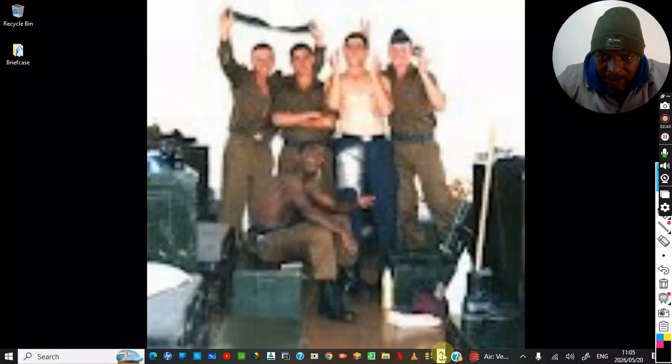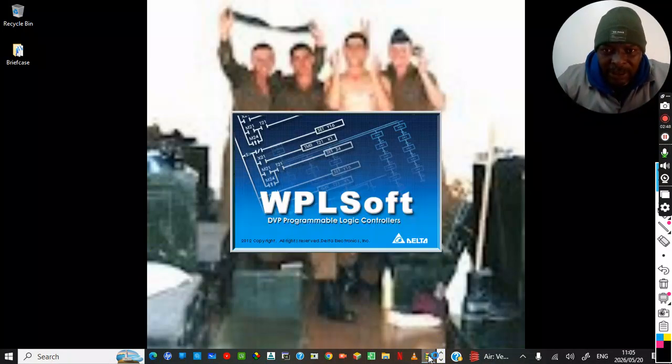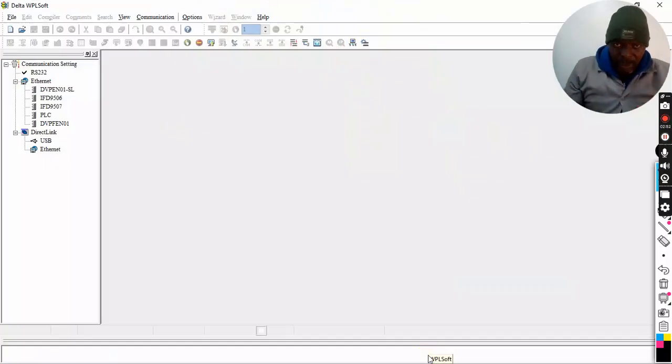Let's bring in our PLC. We'll go down and get our WPLSoft there, and then I want to use this platform, before I open a new page, to basically go to the traditional way of doing the star delta. Now, what the star delta was, I'll draw it here.